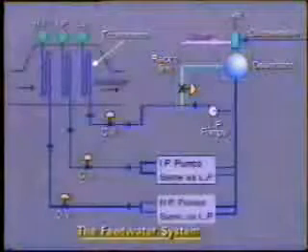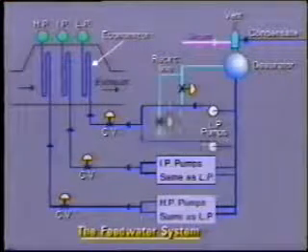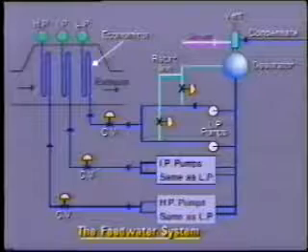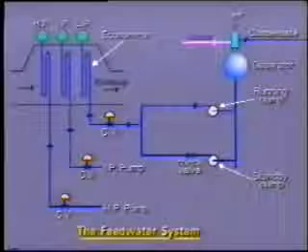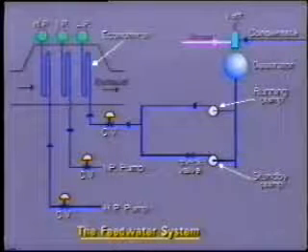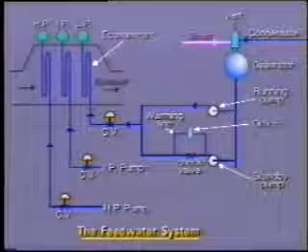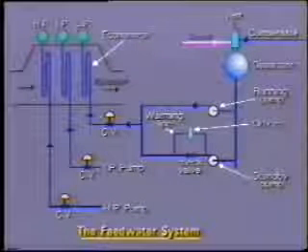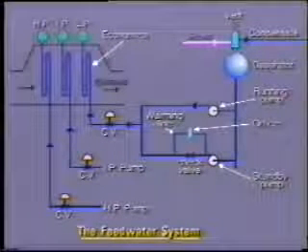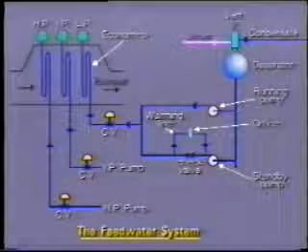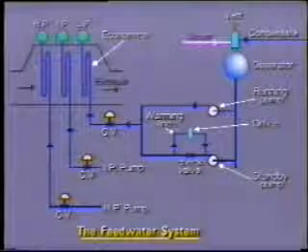The feed pump is such an important part of the system that 100% standby is normally provided. This means each pump is duplicated. The standby pump should always be available and ready to start automatically in case of failure of the running pump. On many installations, a warming line is fitted so as to make sure that the pump is indeed ready for immediate operation. The warming line allows a very small quantity of water to bypass the check valve. That is, it allows a small quantity of hot water to flow from the discharge into the pump.